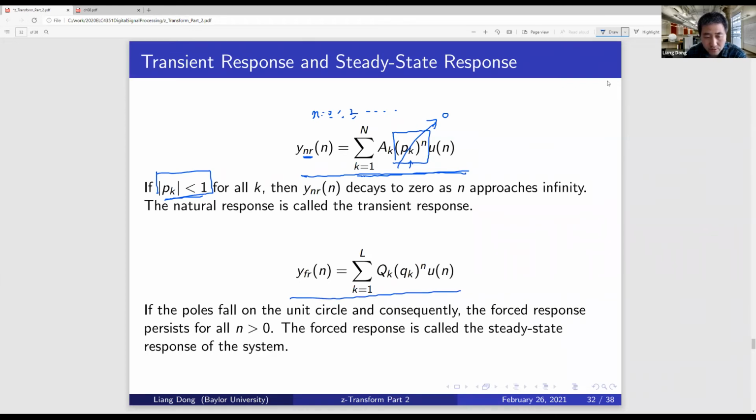So if the poles are on the unit circle, now why do we do that? Well, it's your signal. The signal itself is not going to diverge. You're not going to provide me with a signal that becomes larger and larger without any limit. It's just physically impossible, right? So the worst thing you can have is a signal that never ends. It's a sine wave, and most likely that's the case. You provide some oscillation. This oscillation is always there. You have a sine wave, a cosine wave. So the poles are on the unit circle.